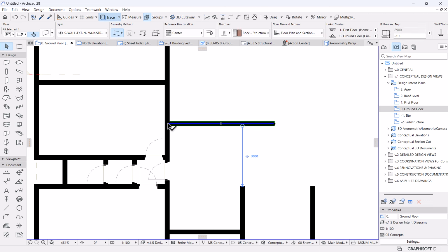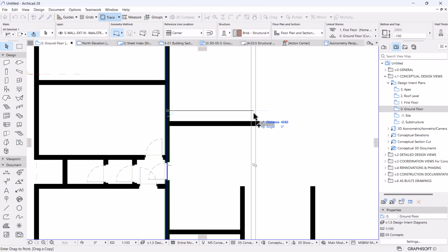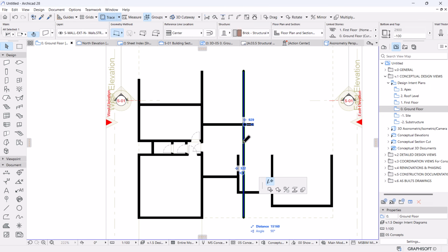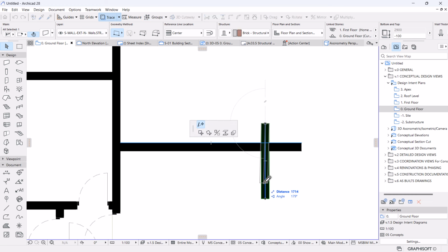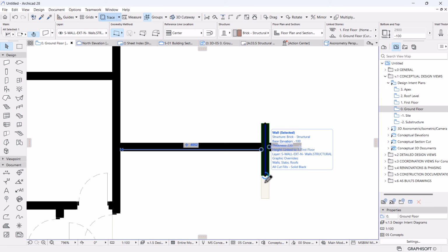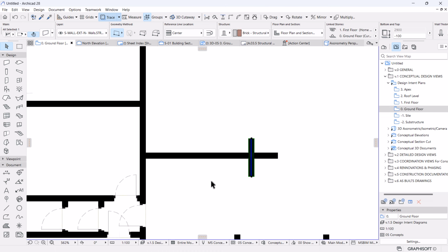And then with this wall, I would want to have some walls, for example, on the other side like that. Let me get rid of the door and stretch it somewhere to there. Okay, unfortunately I can't control the length of the wall with a parameter, unlike with the beam tool. So I hope ArchiCAD going forward will introduce this feature where you can control the length of the wall by not just stretching it, but using a parameter. For example, I want this wall to be a certain length. So for me to achieve it, I'll have to stretch it like that, and maybe use the distance issue. I can say 1.5, but this doesn't make the wall 1.5. Oh yeah, it does. Okay, but I will want to have a parameter where I can just select the wall and then change the length of the wall just by the parameter.